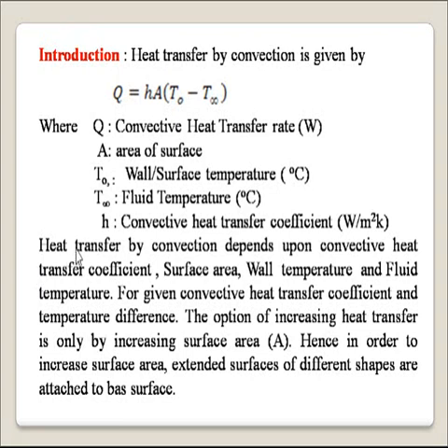Heat transfer by convection depends upon convective heat transfer coefficient, surface area, wall temperature, and fluid temperature. For given convective heat transfer coefficient and temperature difference, the option for increasing heat transfer is only by increasing surface area A.